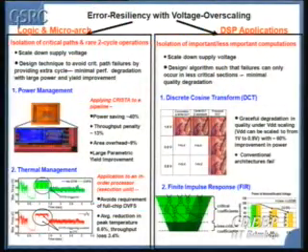So on the error resiliency side, it still shows GSRC, but on the logic and microarchitecture side, one can look at this not just from a lower power consumption point of view, but from the thermal management point of view; the same methodology can really be applied. Think about it. When your computers get really hot, you scale the supply voltage down, but the frequency is also scaled. But in this particular case, the first level of power management can be scaling your supply voltage down, but no frequency scaling. Even after that, if you're still not able to maintain the temperature, then you can do all kinds of standard DTM, thermal management.